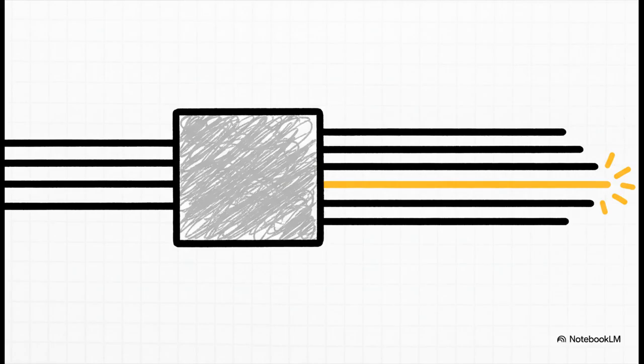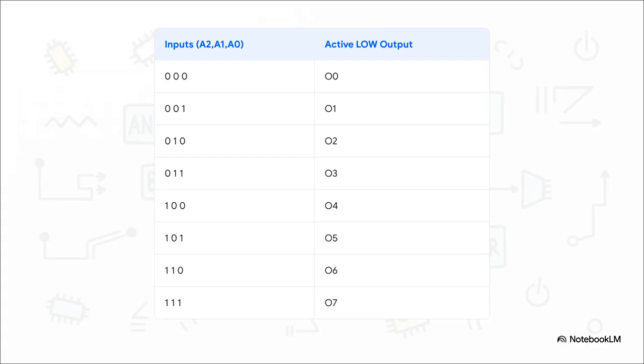And this little diagram just explains it perfectly. On the left, you've got your n input lines. They carry a binary code, kind of like a street address. The decoder reads that code, does its thing, and then activates only one of the 2 to the n output lines on the right. It's a specialist that, when given a code, points to one single destination. That's its whole job.